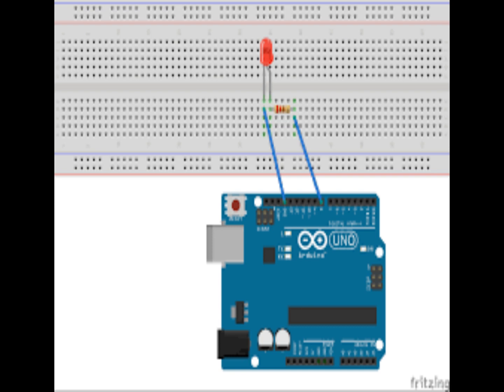In general, the drive current for an LED is 5 to 20 milliamperes. That is why it usually needs an extra resistor for the current limitation to prevent damage to the circuit. Keep in mind that both of its 2 pins are different, and if you connect the wrong jumper wire to one, then the project will not work.